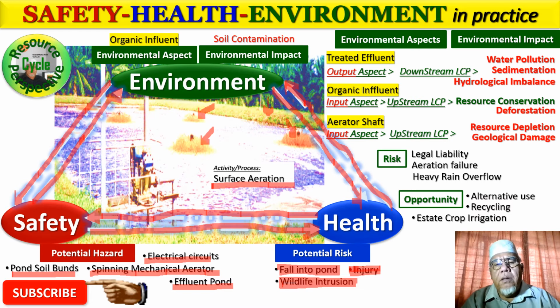COD could be 800 to 1,000 depending on the content of lipids especially. And suspended solids is also quite high, about 700 to 800 milligram per liter, and we've got to bring it down to standards.